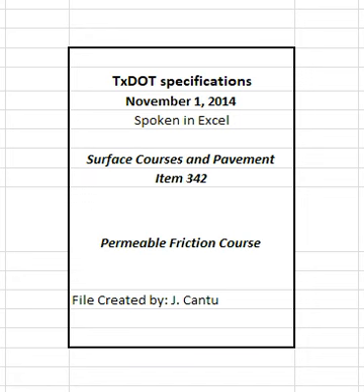4.7.2 Tack coat. Clean the surface before placing the tack coat. The engineer will set the rate between 0.04 and 0.10 gal of residual asphalt per square yard of surface area. Apply a uniform tack coat at the specified rate unless otherwise directed. Apply the tack coat in a uniform manner to avoid streaks and other irregular patterns. Apply a thin, uniform tack coat to all contact surfaces of curbs, structures, and all joints.